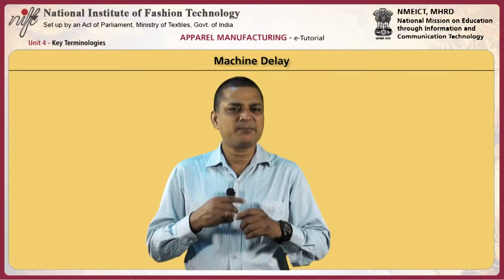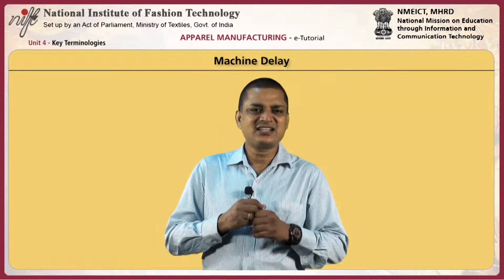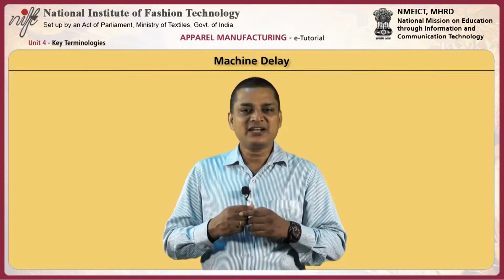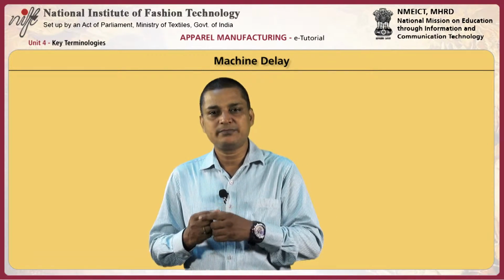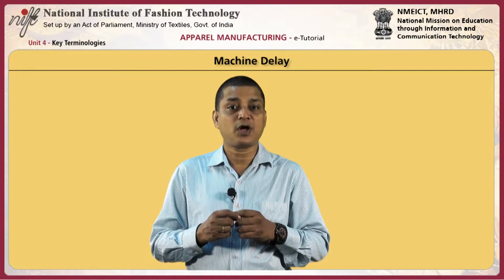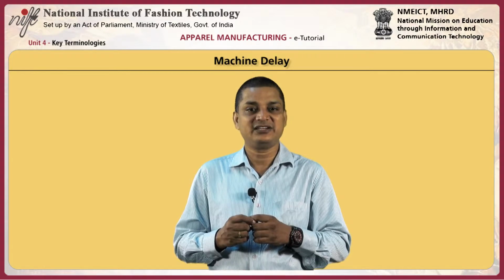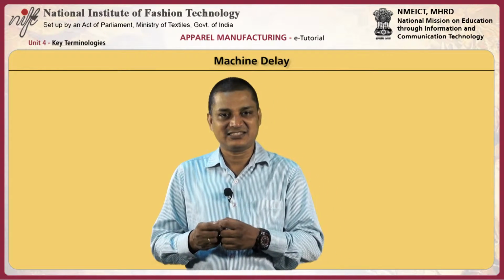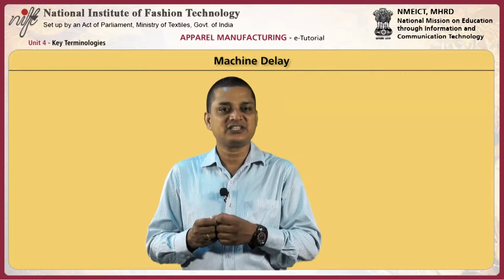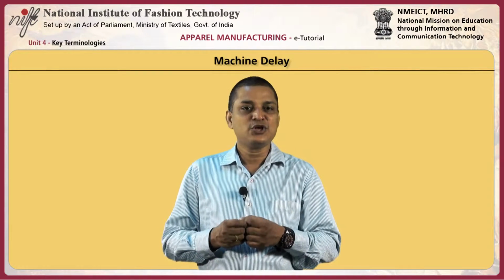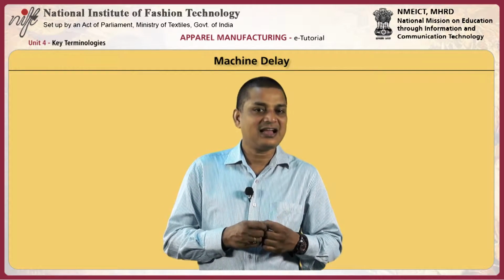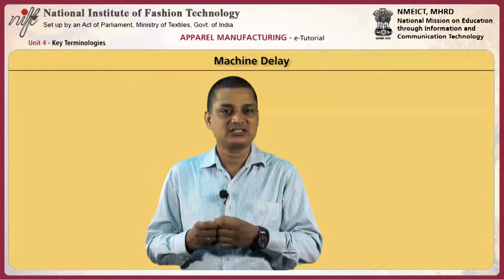The machine delay factor is applied to total cycle time. This has the effect of giving a delay allowance on manipulating elements within the machine cycle, such as pickup garment. On an average, this does not present a problem since the percentage has been developed from actual experience. However, a job with an unusually high or low percentage of pure work in the cycle would merit a discretionary adjustment to the factor, and the engineer is expected to be alert for this.